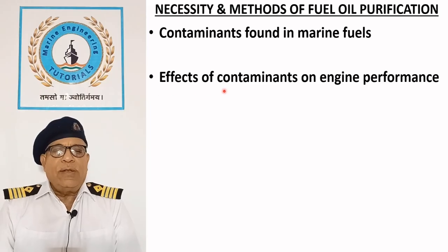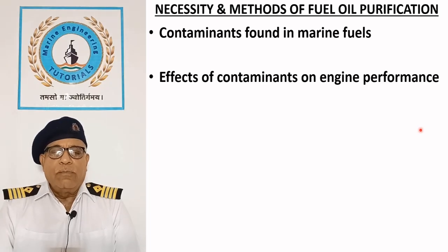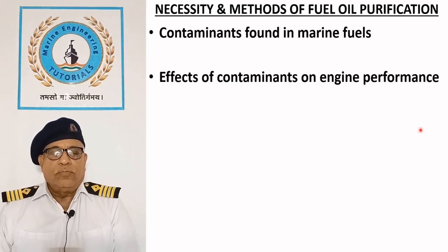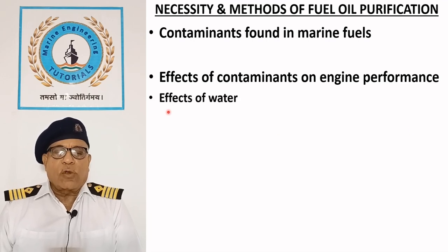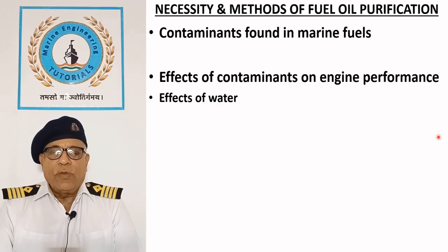Effects of contaminants on engine performance. Contaminants in marine fuels may cause corrosion, clogging of filters, excessive wear of components, combustion, and emission related problems. Effect of water. Water causes corrosion of fuel pumps, injectors, and pipes.